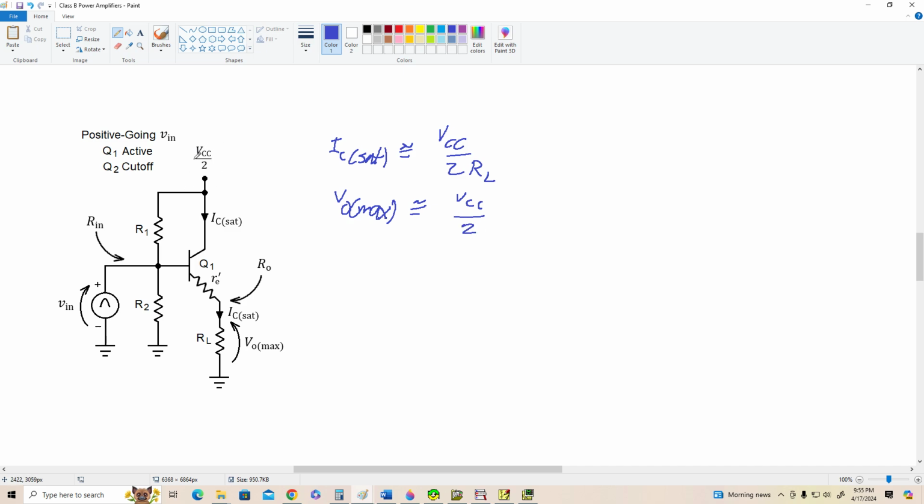If the transistor saturates, we're just going to get this supply voltage, VCC over 2. And remember, I'm using VCC over 2 because we've got C2 charged to half of the power supply voltage down here, and with VCC up here and VCC over 2 down here, it just works out easier to represent it this way.